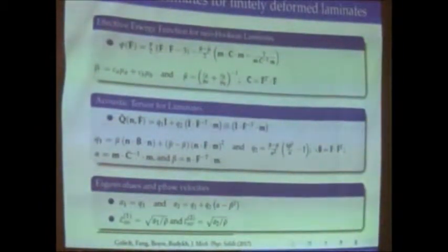In that way we obtain the long wave estimate for elastic waves, for shear waves here. Everything is expressed in terms of micromechanical parameters. We use just the properties of the phases and the volume fraction, the concentration of these. So no fitting, just give us the information on what the materials in the composite are, and that's the estimate in long waves.